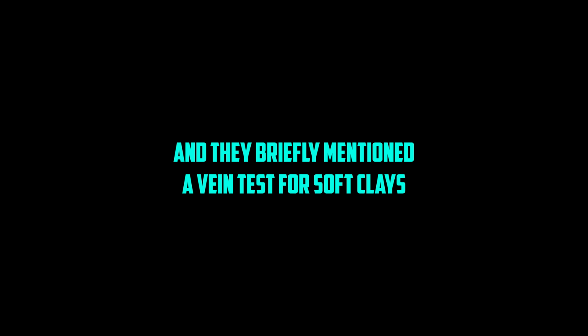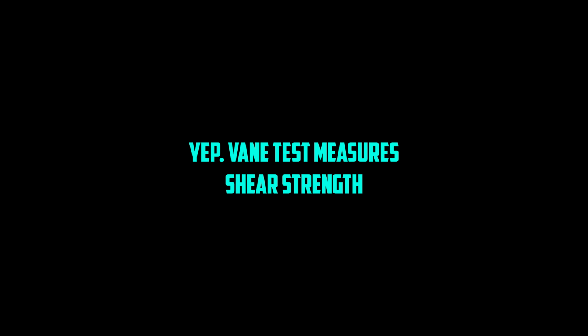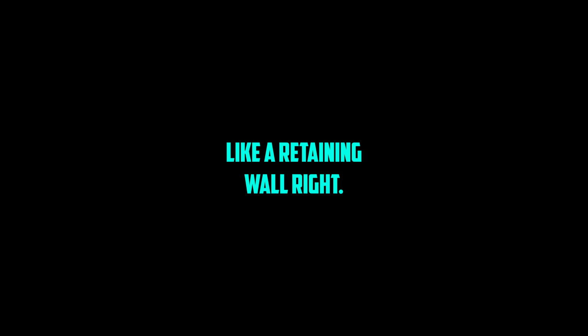Okay. And they briefly mentioned a vane test for soft clays and bulk density for designing retaining walls. Yep. The vane test measures shear strength directly in soft, cohesive soils. Bulk density, just the mass per unit volume, is crucial when you're calculating the weight of earth pushing against something like a retaining wall. Right.